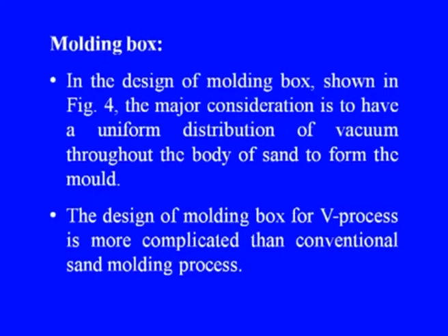In order to ascertain the perfect matching, the pattern plate having equidistant holes is provided with 4 support blocks at the 4 corners of the pattern box. Additional support at the center has been provided to prevent warping of the pattern plate when subjected to vacuum pressure. The pattern box is fixed to the vibrating table.